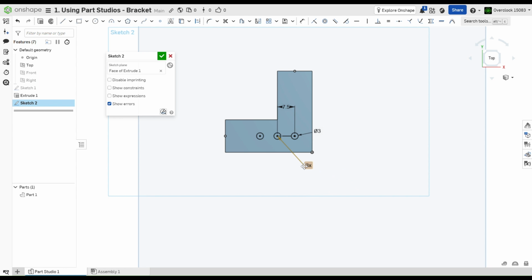And right here, it's only doing 3 holes. So this box, you can double click on it in order to edit it, and then bump this up to 4 holes, since that's what we want on our bracket. And so now we have our horizontal holes, but we'll also want some holes going up vertically. So you can click on linear pattern again, click on the circle, and we don't want them going horizontally, so we want to set the count horizontally to just be 1.